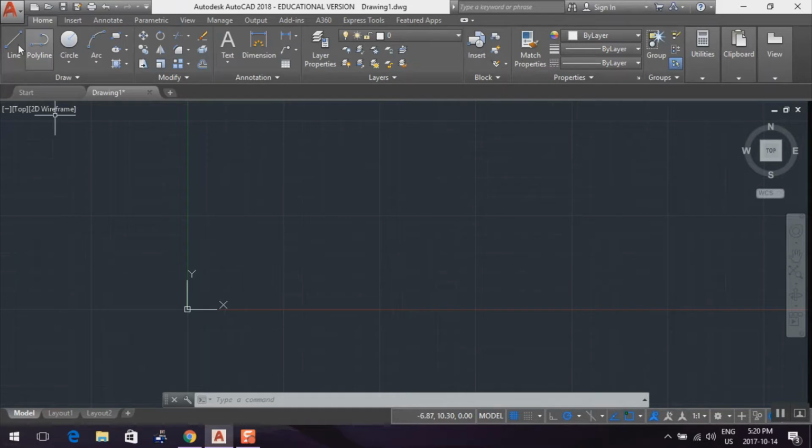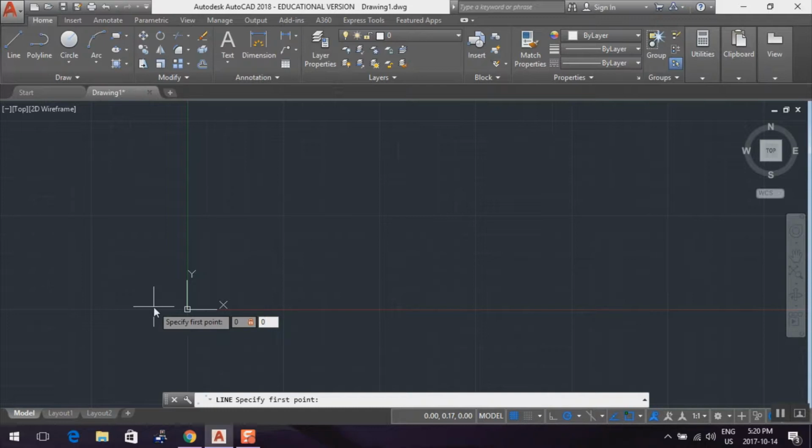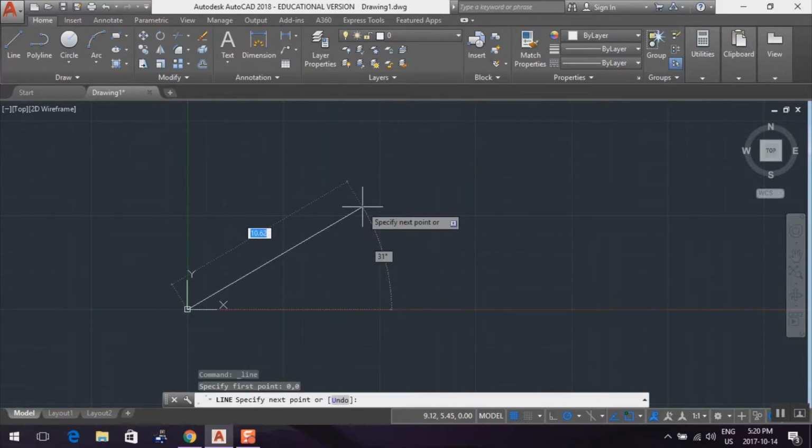And we're going to create a big rectangle, and I'm going to show you how to do that, which would be the start for, I guess, if we were making a bridge. I'm not making any particular bridge, but so I've got my line. I'm going to push 0, 0, and it puts the starting point right at 0, 0, okay, of this line.